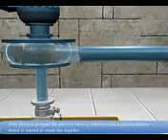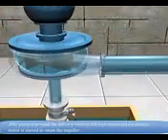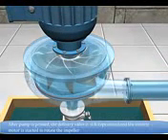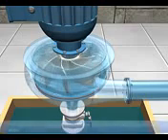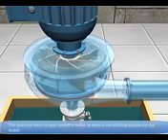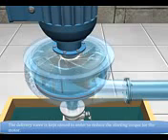After the pump is primed, the delivery valve is still kept closed and the electric motor is started to rotate the impeller. The delivery valve is kept closed in order to reduce the starting torque for the motor.